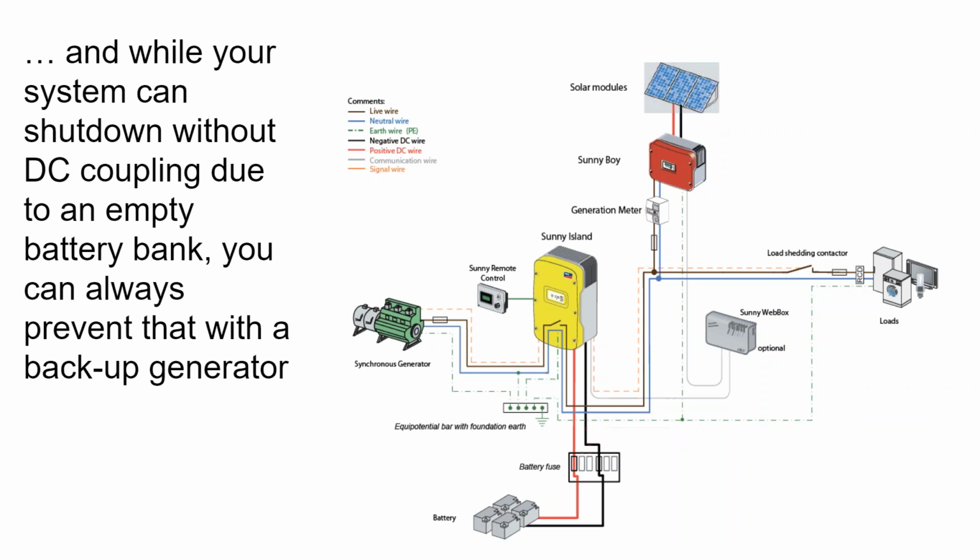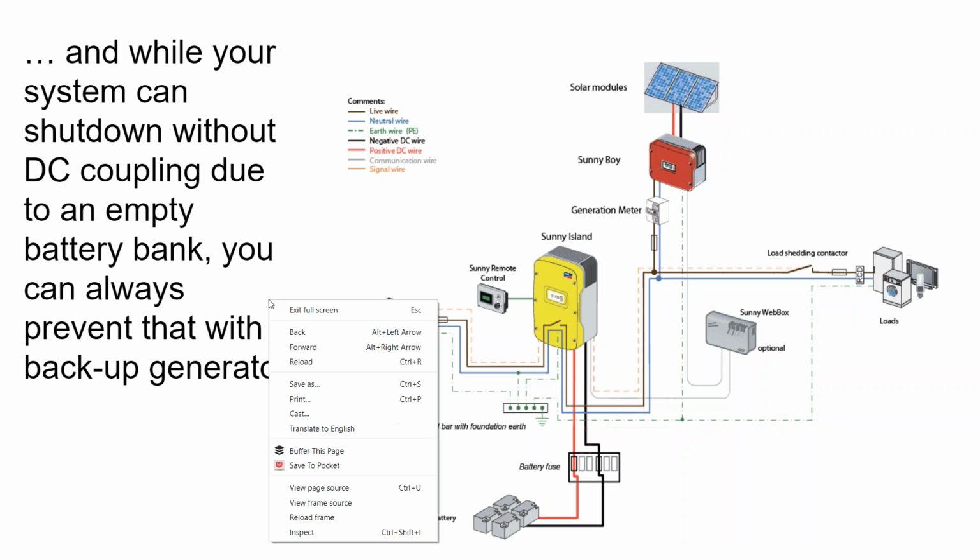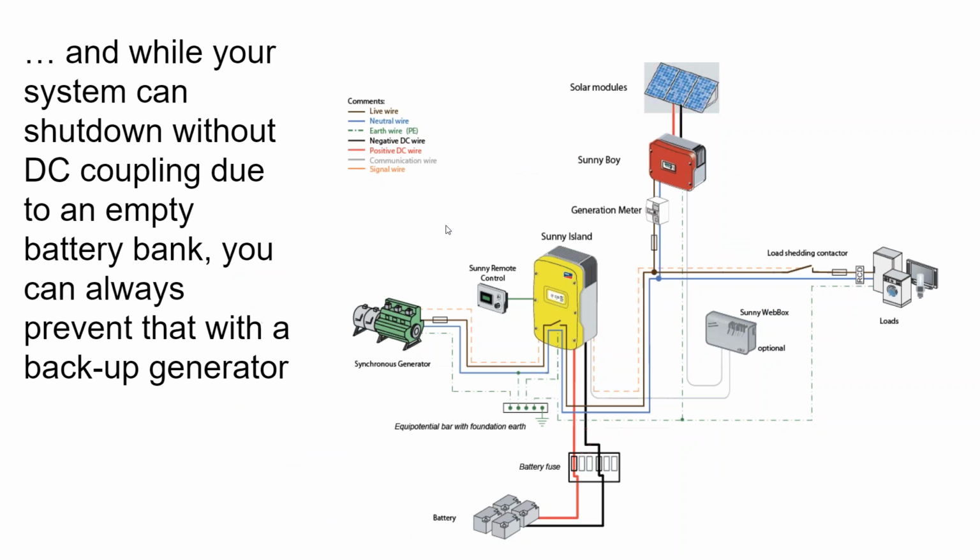It's just going directly into the load. On the other hand, if you're in an off-grid situation where you're primarily running off the battery, then it's a little bit more efficient to just feed the solar directly into the battery and not have it go through the number of processes it has to go through for getting the energy to its final point of use.